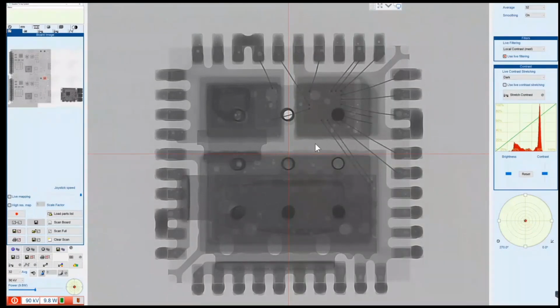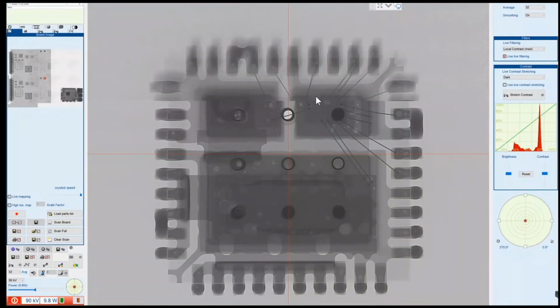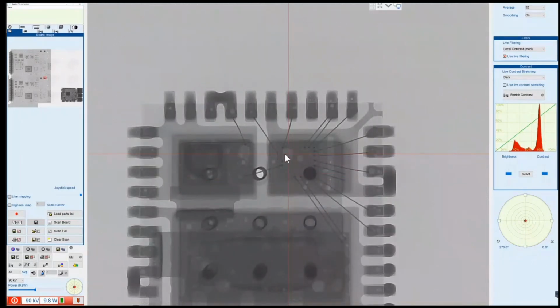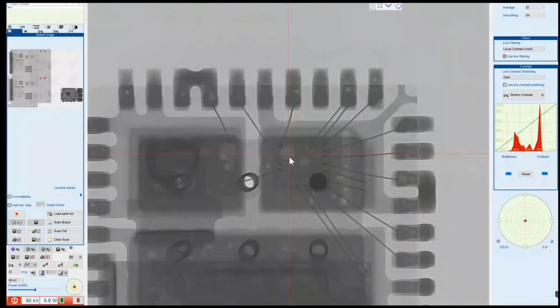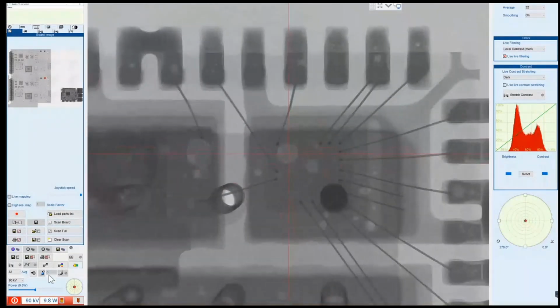And when you're using a local fiducial, what you're looking to identify is a feature which is circular, not going to be obstructed much, and can be used as a local fiducial. So I've identified this void over here as my potential fiducial point. So what I'm going to do to begin with is set the height on this.